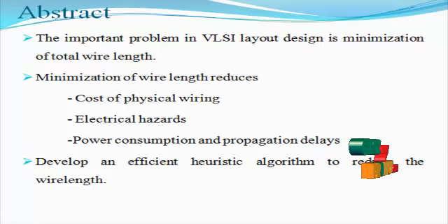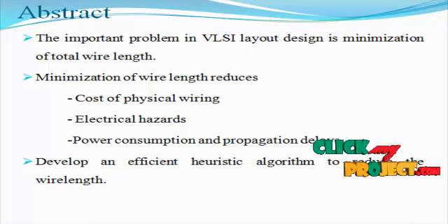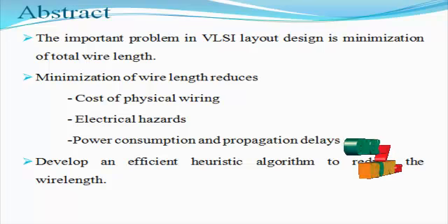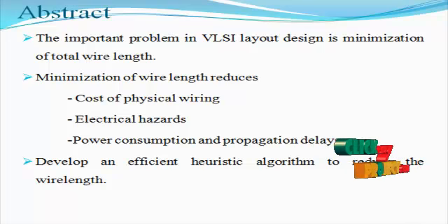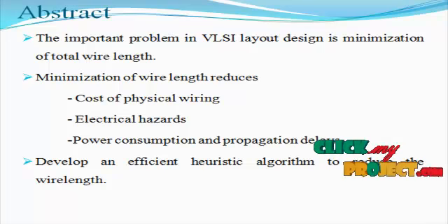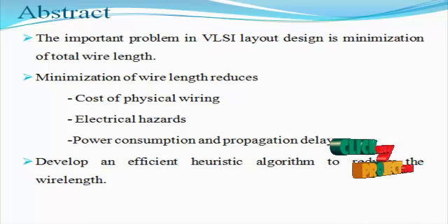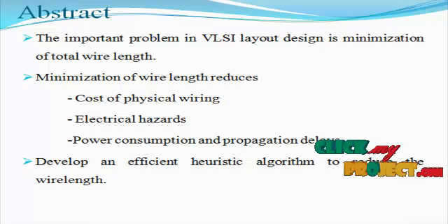Next, we see the abstract for the product. The channel routing problem is an important step in the layout design of VLSI circuits. Channel routing with the minimum wire length reduces the cost of the circuit and the delay of propagation signals, and gives better electrical performance. However, the channel routing problem of wire length minimization is NP-hard. There are several channel routing algorithms that have been developed to minimize different costs of the channel routing problem.